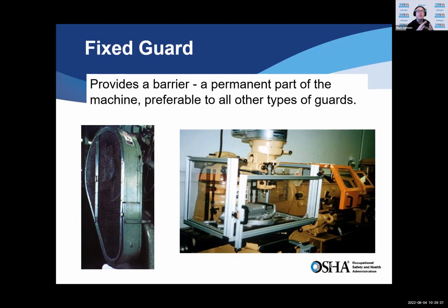The requirements for the openings on that expanded metal, let me try to use my hands here. If you've ever seen that, it's sort of a grid pattern. There are some requirements about the openings, right? How big is the opening allowed to be on that expanded metal? And I said, well, I can give you some numbers. And again, you're trying to prevent access or someone from getting caught or hit with the moving parts.